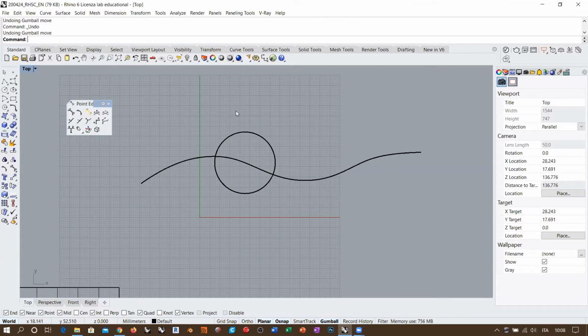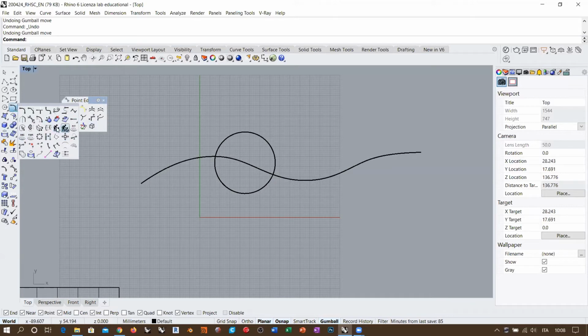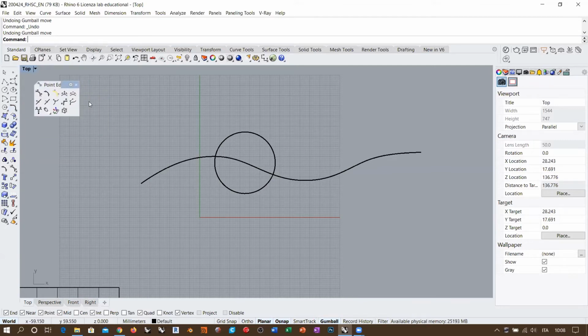We don't need to add complexity or to simplify the whole path of our geometry or the whole surface. Okay, so I do recommend that you work with this toolbar before then the global curve tools, which in this case are the rebuild commands. Okay, so try to familiarize with these commands, because these are the key to a smart topological modeling in Rhino.